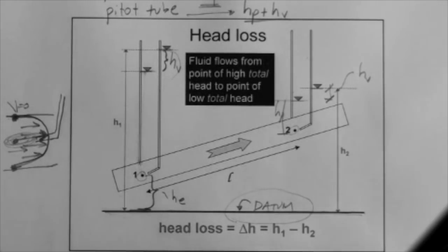Now in the exams I will tell you what to use as a datum, because if everybody selects a different datum, then everybody will have a different procedure in terms of calculation, but hopefully if everybody is correct, the answers will be the same. Remember, it doesn't matter what datum you select. If you select a datum that is up here, and I select a datum that is down here, and we do the problem, we're going to get the same answers for the case of total head.